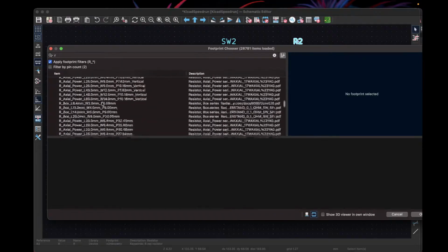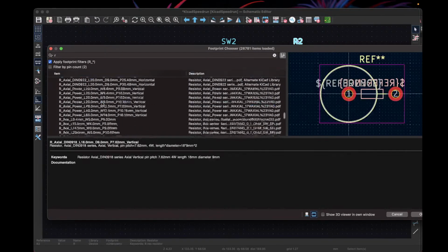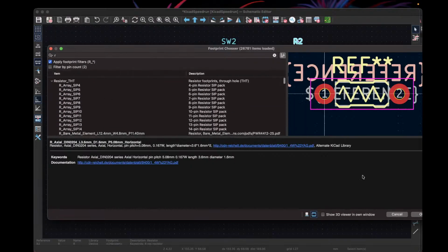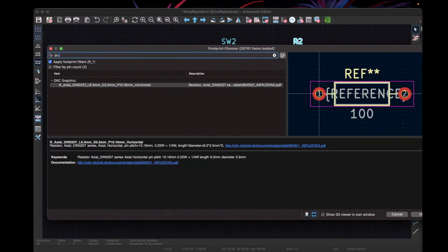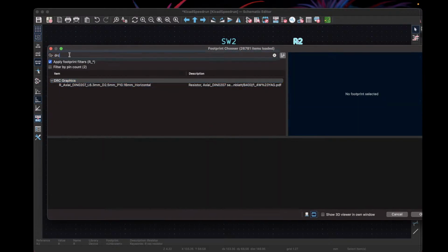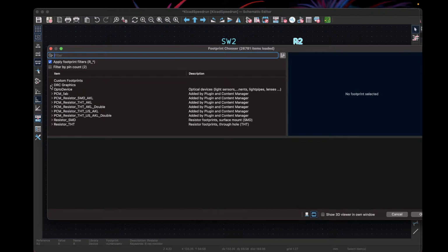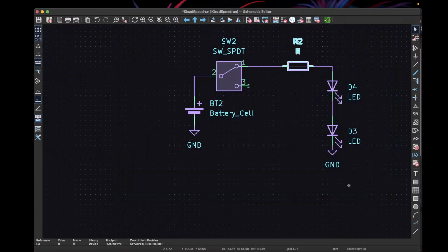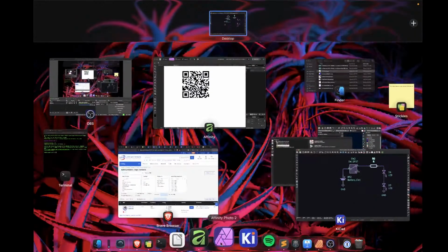Like, there's hundreds of them. So it really is good, in the beginning, to narrow down what it is that you want. For me, I have my own library of parts that I commonly use. You find the parts first, and then given those parts, you create the... Ideally, yeah. You probably want to pick out the components first and then get the footprint to match it. Okay. That's usually what I do.